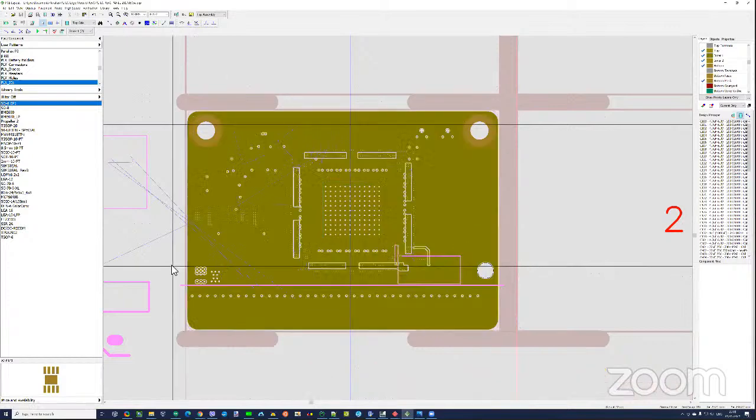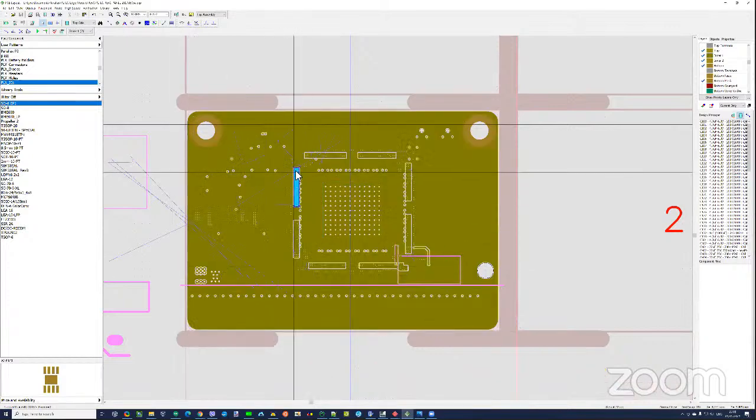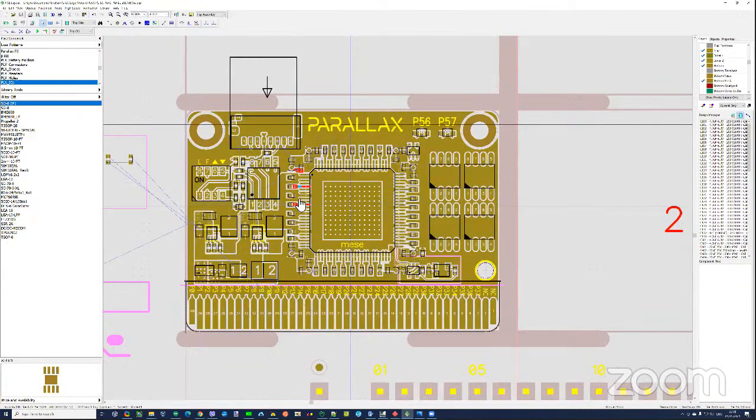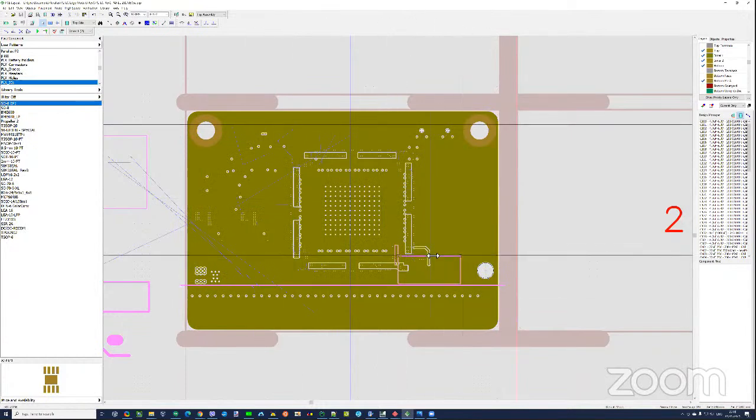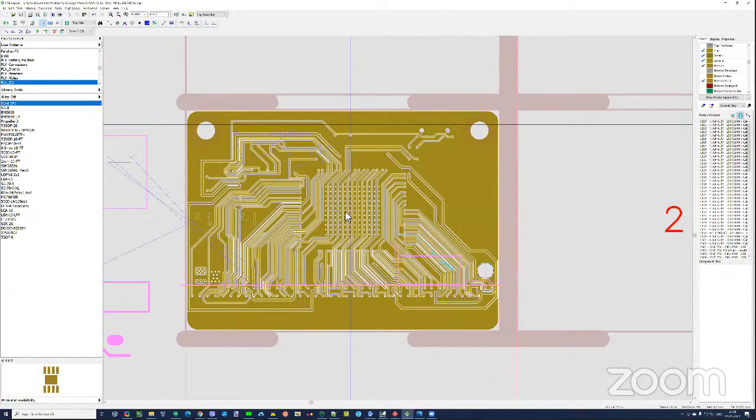And then layer 2 is just ground, apart from the straps across for the 3.3 volts coming out of the LDOs into the P2. I need to look at those at the end of the process to make sure we're not crossing any planes in a nasty way, but otherwise that's all solid plane. And there's a little 1.8 volt trace there feeding into the crystal circuit. And then we'll have the core, and then layers 3 and 4. 3 being the signals. All the signals are on here. Again, don't worry about funny looking right angle traces. They've just not been routed in yet.